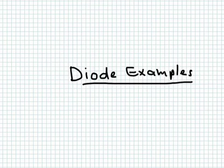The most important thing to remember here is that the diode can be in one of three regions: forward biased, reverse biased, or the breakdown region. And as we did before in all examples of active devices, you have to assume a region of operation and then verify it. So let's take a look first at the theory and then we'll move to discuss the examples.